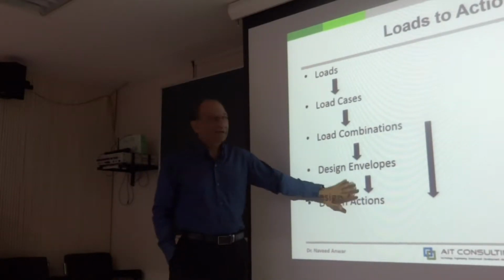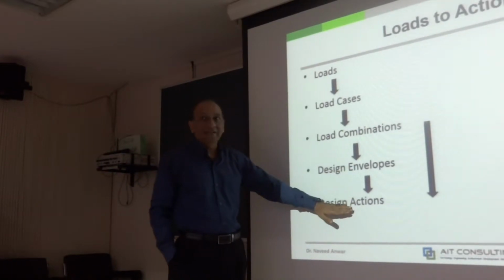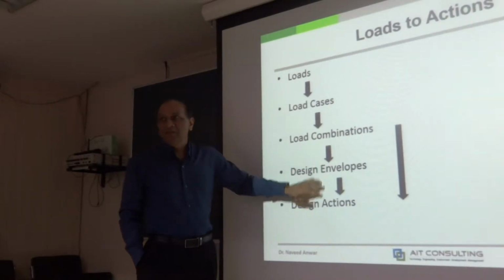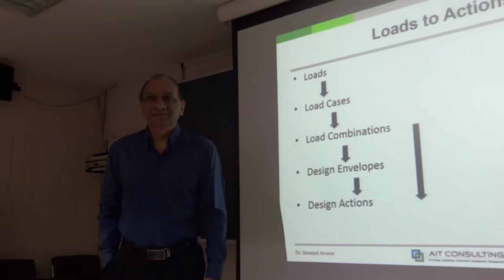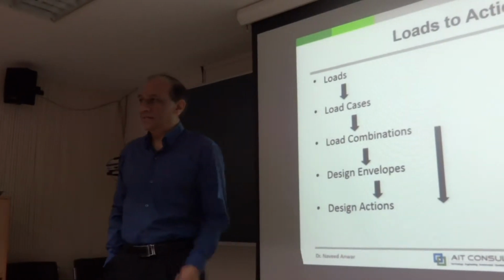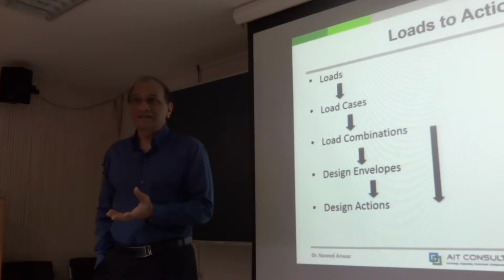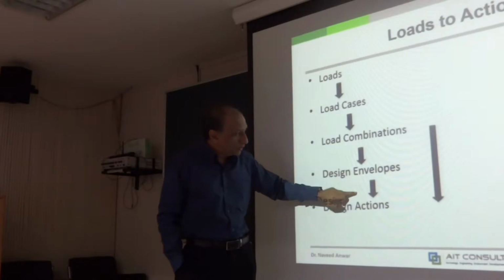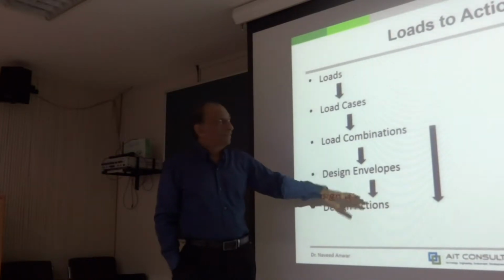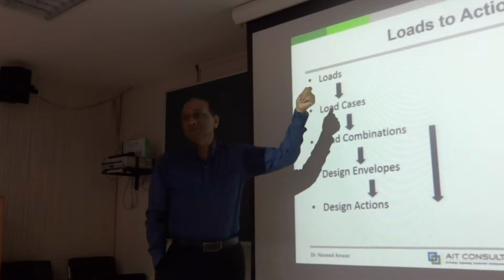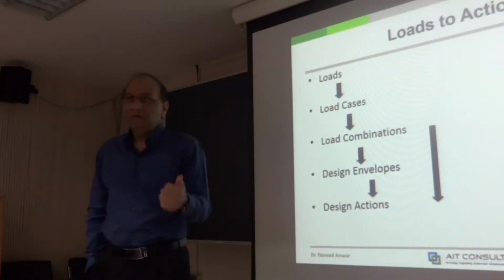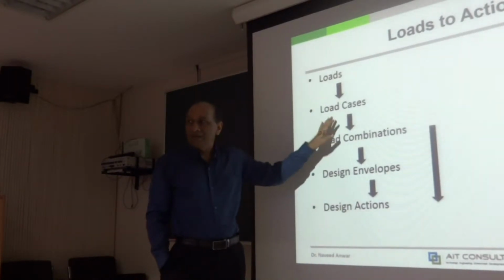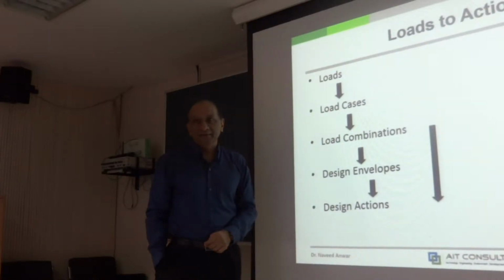So, design actions, we come from load combinations and directly we can go to design action, and we skip the envelope part, which may be relevant for steel, which may be relevant for pre-stressed concrete. Last time we talked about that. The pre-stressed concrete is just like elastic material. Interaction is not really considered, so elastic envelope can be used there. So sometimes we go through this one, sometimes we jump like this one. But the whole process, what loads you will use, what cases you will use, what combinations you will use, and what design actions you will use should be described clearly in your design criteria.